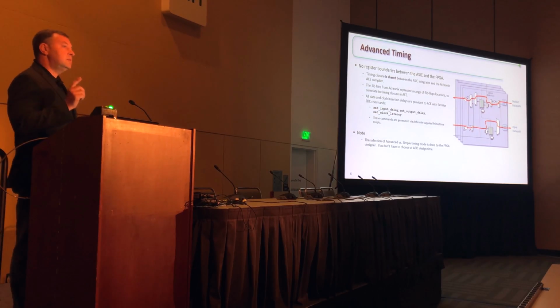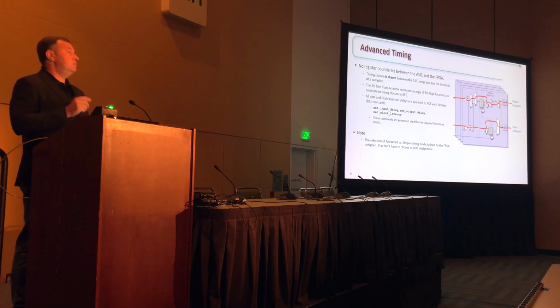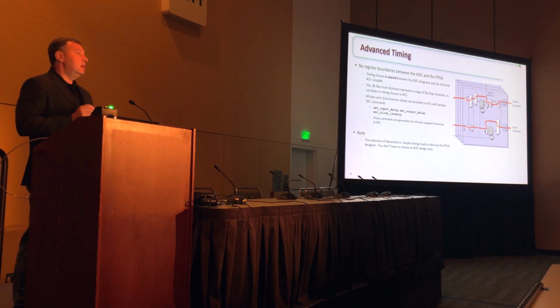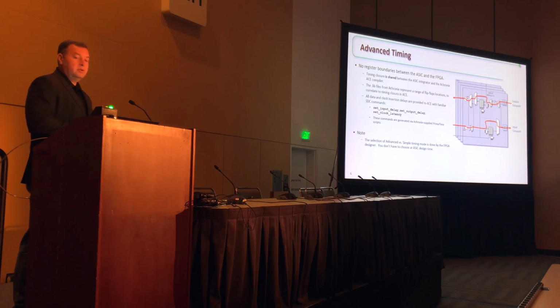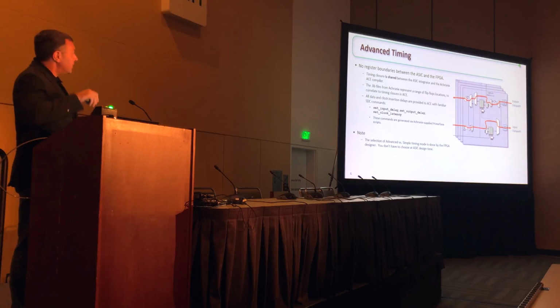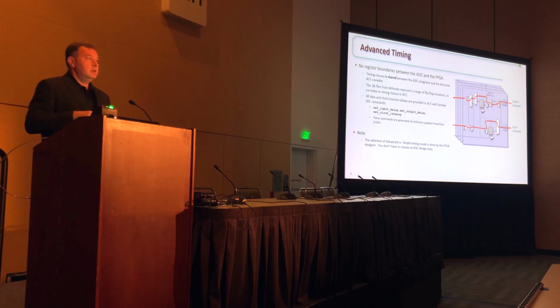So we have this one timing path that's owned by two different people that importantly are closing timing at different points in time. The ASIC designer, of course, has to finish all of his work long before tape out. The FPGA designer, he doesn't even really get started until the chip's available to play with, right? So we're sharing this timing path that starts inside the FPGA and ends up here outside the ASIC. We have an equal and opposite timing path that starts here outside the ASIC and ends inside the FPGA. The story is a happy ending.